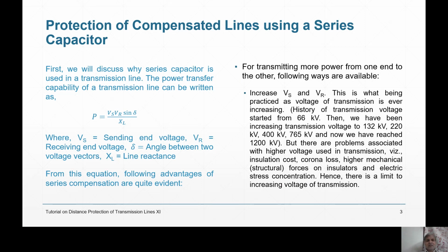What can you do? So people have found out a way: connect a series capacitor, not only XL. I am talking series capacitor, my friends. Don't make the mistake with shunt capacitor. I am not talking about shunt capacitor, which is used for power factor improvement at the receiving end. I am talking of series capacitor.